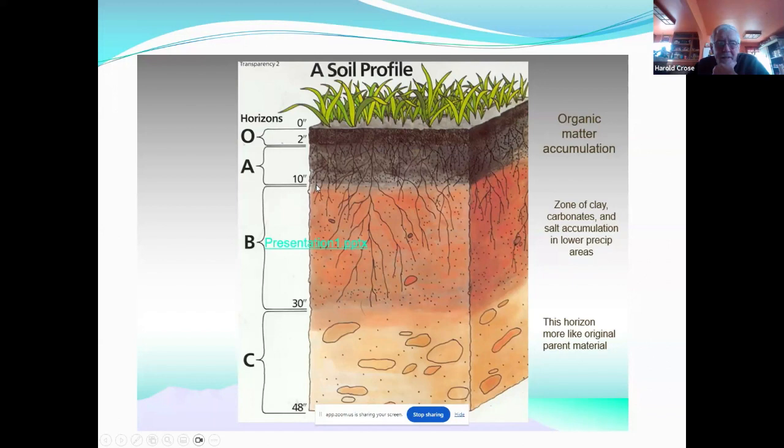Typically in any given crop, 75% of the root mass is in the top 25% of the root zone. Up here in this area is where the crop is taking most of its nutrients, getting most of its water. And so protecting this layer of soil here is just critical. But we manage water for the root zone of the crop.